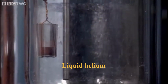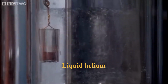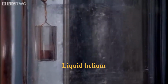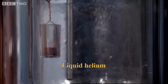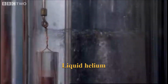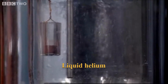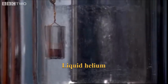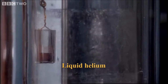On the other hand, in the case of liquid nitrogen, the gas density at its boiling point is 0.0046 grams per milliliter, which is much less than 1% of the liquid density. The boil-off impact of liquid helium is much higher than that of liquid nitrogen. Why nitrogen behaves differently? Higher liquid density means volume estimates are reliable. Lower gas expansion effects make displacement negligible. The higher latent heat of vaporization slows down boil-off. Helium requires precise handling due to rapid evaporation and its compressible gas phase.